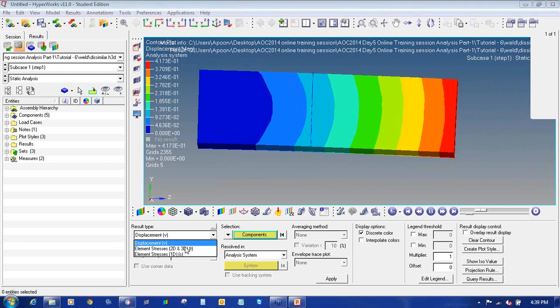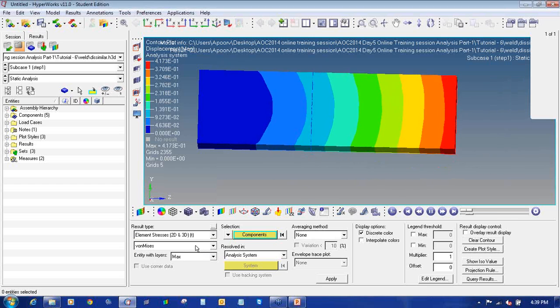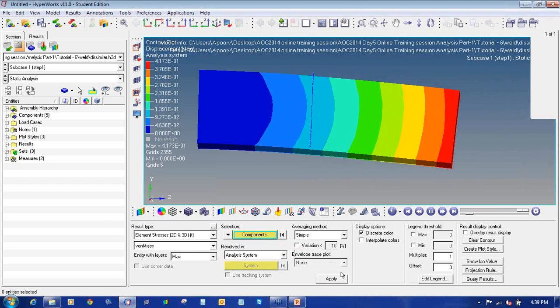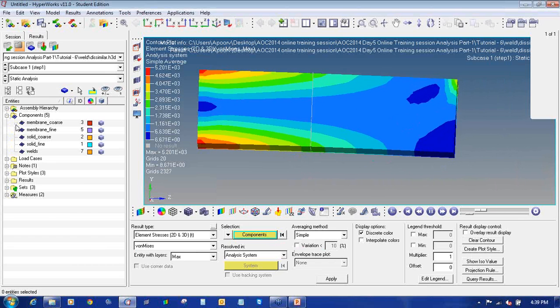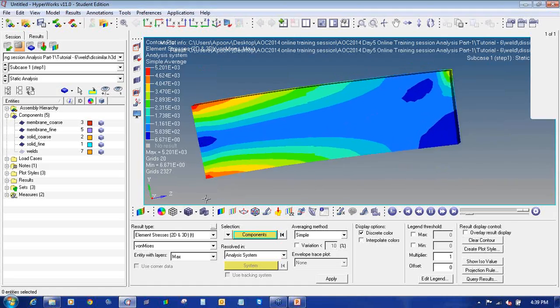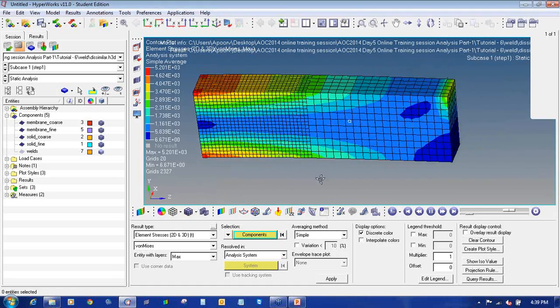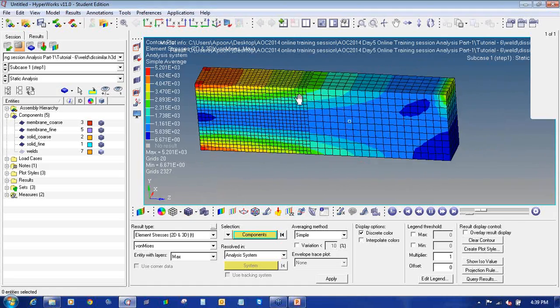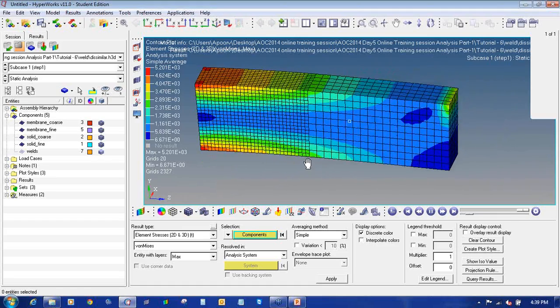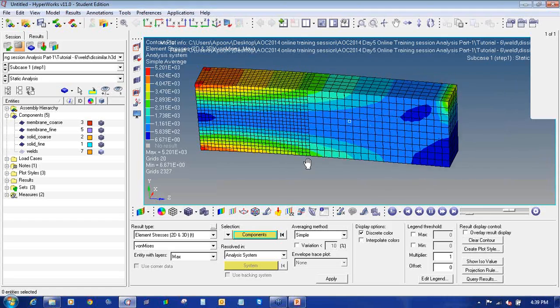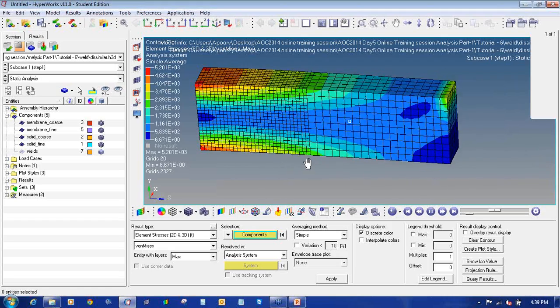If there is no connection, the analysis will not perform. So I can off this weld elements. So now it is of no use. And if I on this meshing, so you can see even the meshing is not connected, still the analysis can be performed by connecting those using weld elements.